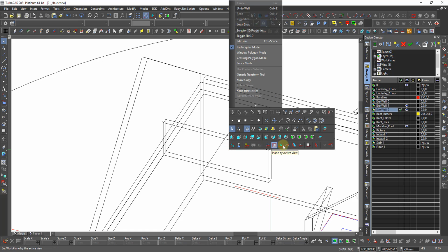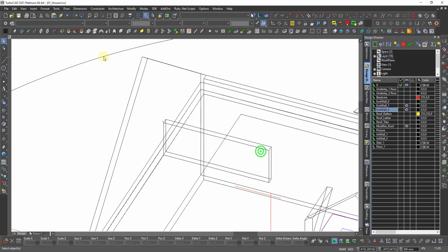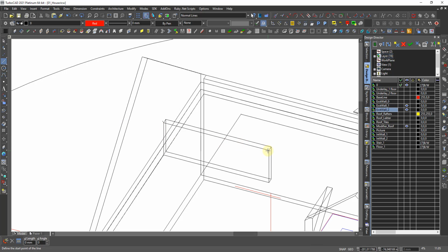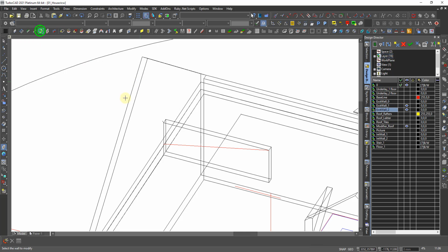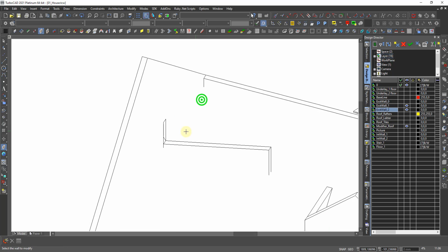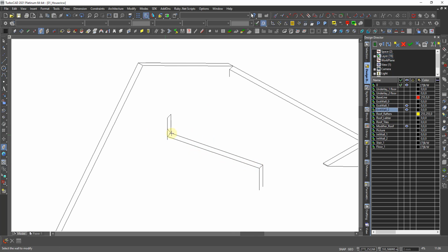I say work plane by face on this, and I draw a line from V to nearest here, maybe, to M, and then I use top wall modifier, select the wall, and I select this, and that is what I call a trace mark, or the hidden mark, because the wall is there, it's just hidden, and then it will make this mark on it.